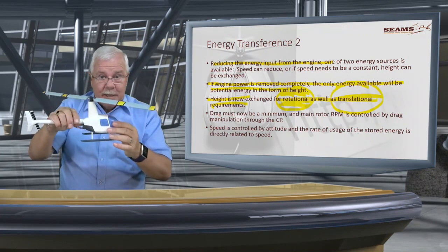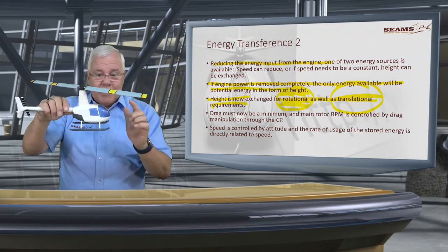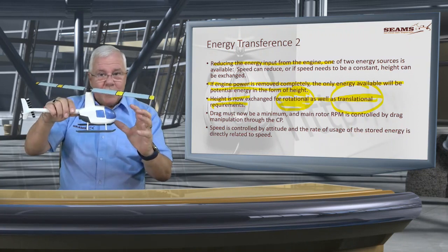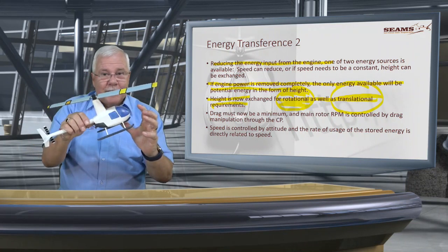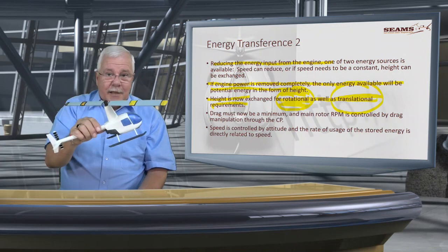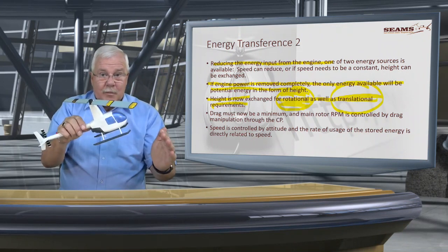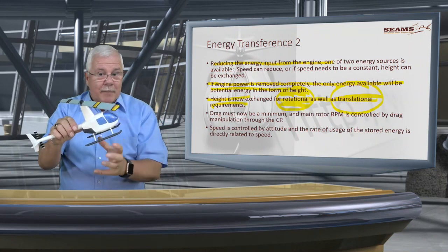So as you're coming down with a helicopter, you've got 65 knots forward speed, and you can take it into a flare situation to break the vertical speed and the forward speed, because there's a rate of descent and there's a forward speed. Okay? You want to reduce both of those.